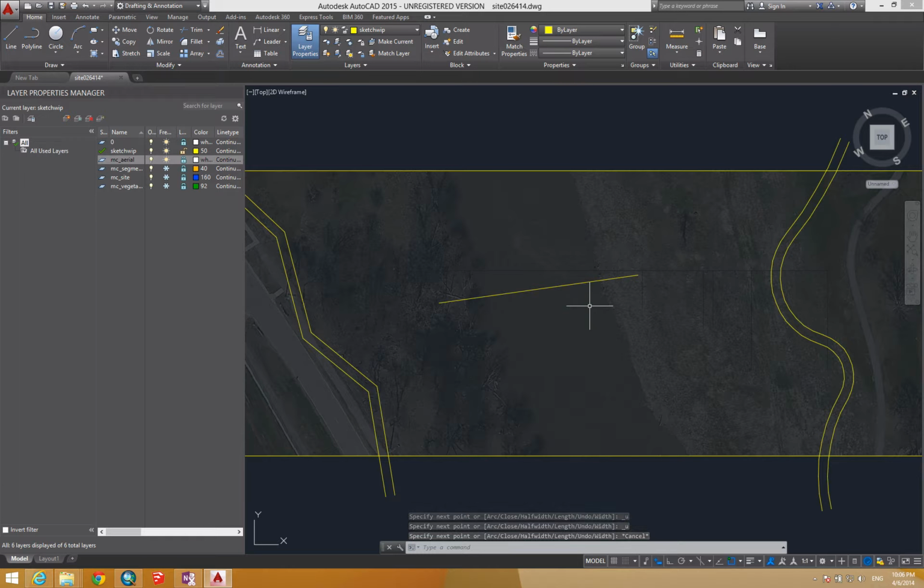This could be the center line, it could be an edge. I'm just doing schematic, so we'll just consider it an edge and we'll connect the rest of the pieces. Alright, so let's do polyline again. This time I will select the end point, and once again I'll hit A, enter. And look at that, a nice tangent arc from that last point.